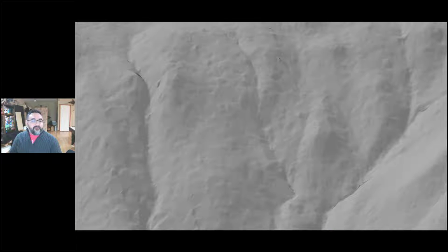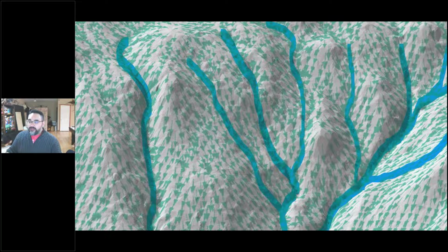As we look back to the landscape level, this is just a typical DEM of a slope. And as it rains, water comes down, hits the slope, and it hits the ground, and it starts to infiltrate and disperse. So these are just flow lines that are draped over the TIN. But this water is now going to start concentrating into the channels as it flows down the slope. So as it's concentrating in those channels, those get bigger and bigger as they go down the slope. And like I said before, those are developed over time to handle the flows, the peak flows that they're used to.